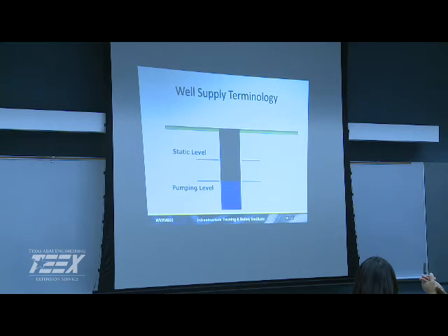But what you can do is they can go in and basically weld the pitless adapter and put a separate pipe out. That's what we do. We had some artesian wells. Basically, when you're not running, you have to put the water someplace, so you don't want it all in your treatment building.